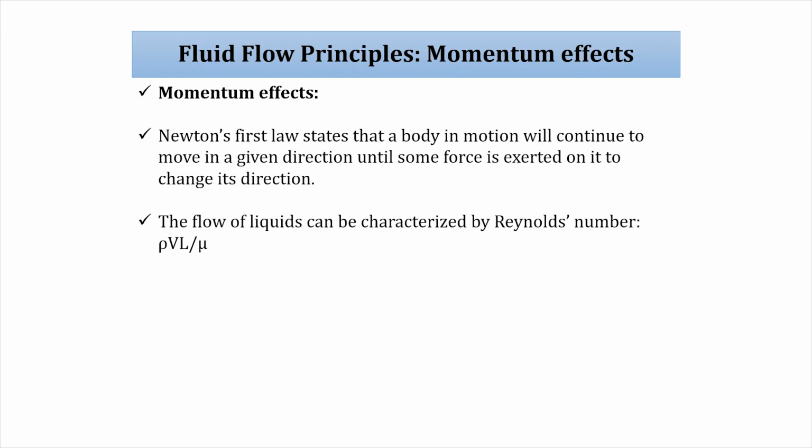Third, in mold filling, the fluid flow principle we apply is momentum effects. Newton's first law states that a body in motion will continue to move in a given direction until some force is exerted on it to change its direction. So, if the inertia force scales as rho A V square, and the viscous force is mu V L into A, then the ratio of inertia force divided by viscous force